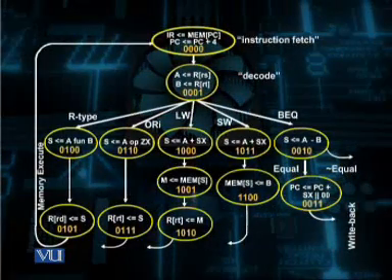For example, in case of R-type instructions, the next step is to write the result back into the required destination register. So the next state is the write back state. And similar is the case with the immediate data type instructions and with the store type instructions.